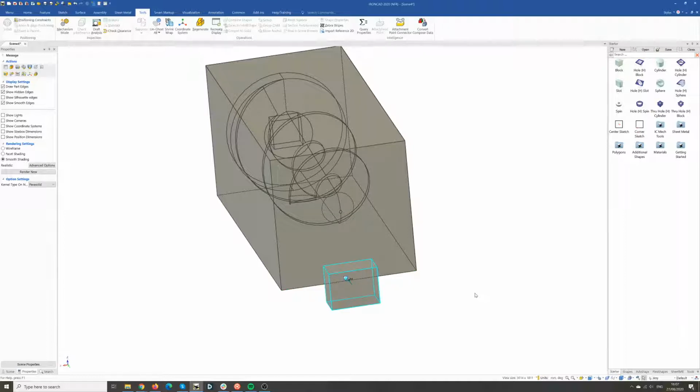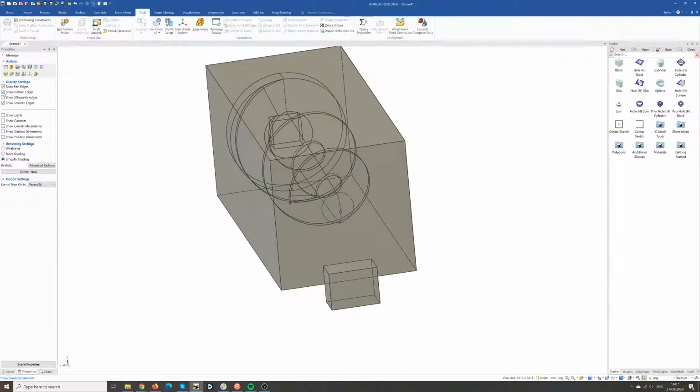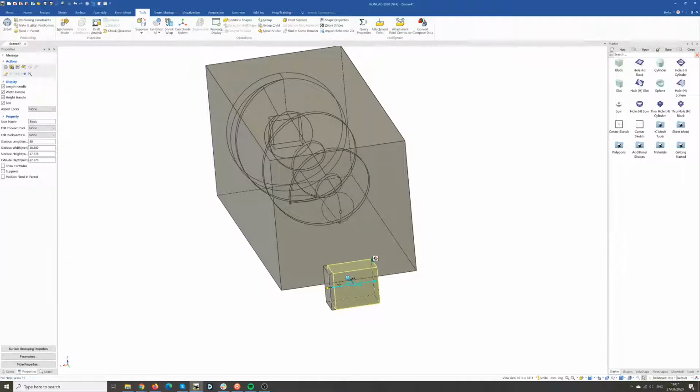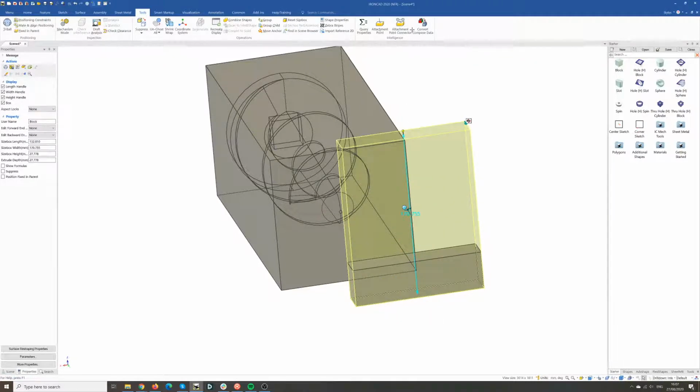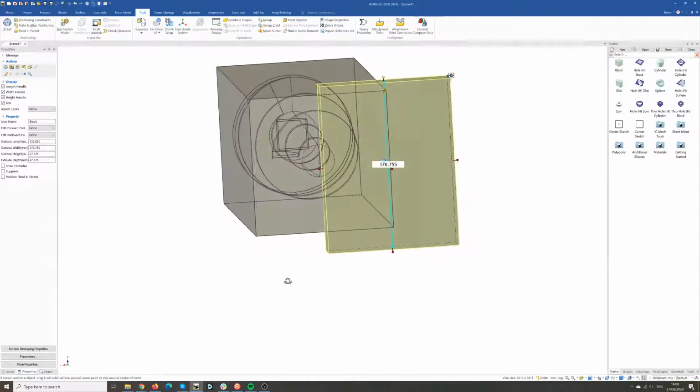I'm going to drop a part, and I'm going to turn the part off. Let's leave the hidden edges on. So pick that one there. I'm going to drag that and put it, shift key down, look for the center point of that line, and I'm just going to take that up above there.